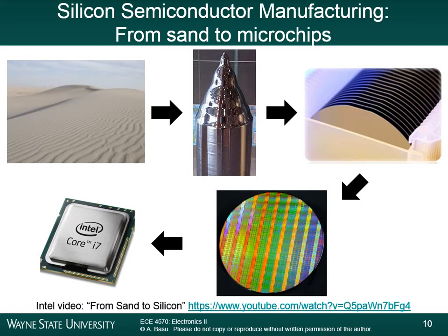Well, when we were talking about overclocking, right? The spec that they give you, if they say it's 2.5 gigahertz, you might actually be able to run it at a higher clock rate if you keep it cool. Which is why a lot of gamers do this. With one of the Intel chips, someone used a liquid nitrogen cooling system and clocked it to around 7.2 gigahertz. Wow, that's remarkable. You can probably go higher if you use a liquid helium cooling system. That's really amazing. So a 3 gigahertz processor clocked at more than 7 gigahertz. 7 to 8. That sounds quite amazing, actually.